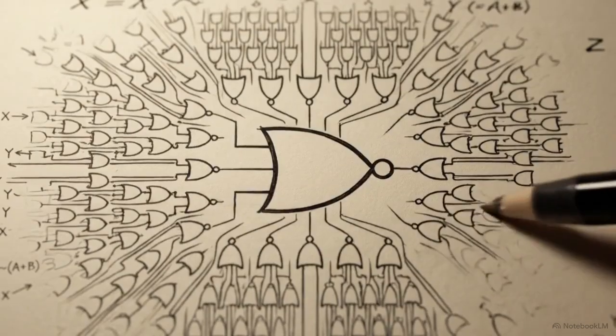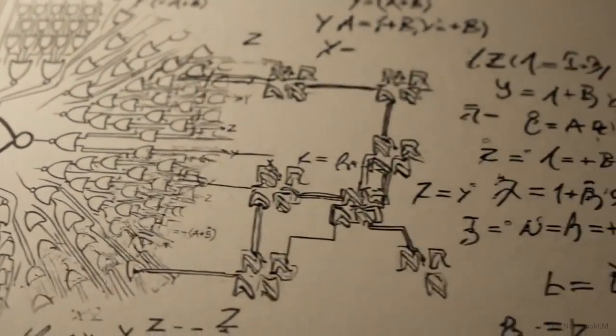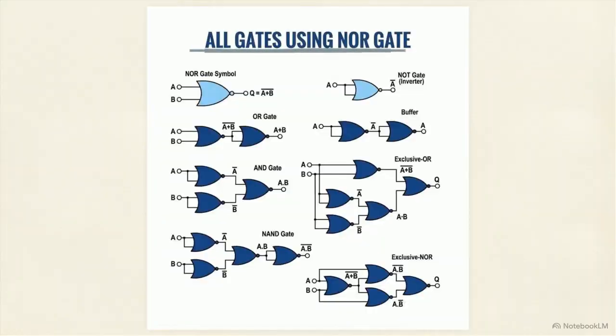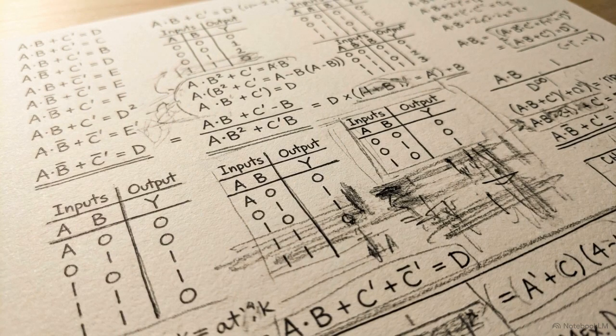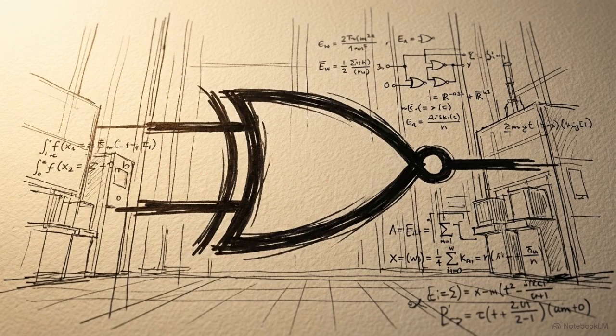We have definitively proven that highly contingent, complex logic systems can be generated entirely by repeating a single primitive mathematical operation. This uncropped diagram reviews the full scope of our derivation. Starting from a single truth table axiom, we successfully derived the NOT, OR, AND, and XOR functions. But chalkboard mathematics is only half the story. The real application of this axiom lies in the physical and economic realities of engineering. Why would designers intentionally restrict a multi-billion-dollar engineering process to only one gate type?